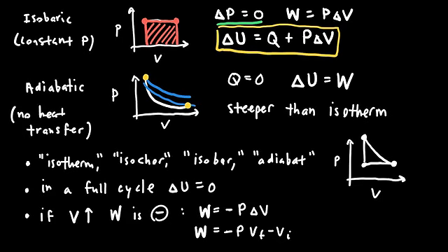And that's quite poorly drawn in that graph because I didn't have a lot of space. But in general, an adiabatic process starts off at one temperature and ends up at another temperature. It is a line that connects two different isotherms, two different temperatures represented by those curves. But it goes from one state to another without any heat transfer. An adiabatic process is defined as not having any heat transfer, and so for that reason Q is equal to 0, which means that any change in the internal energy of the gas is not due to heat transfer, but it's due to work being done.